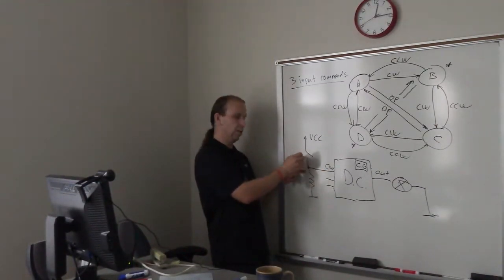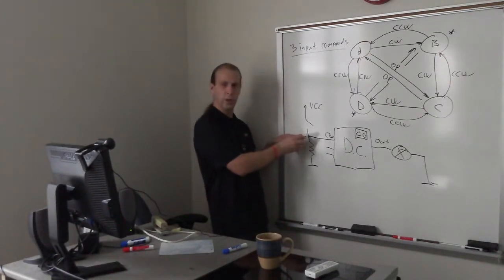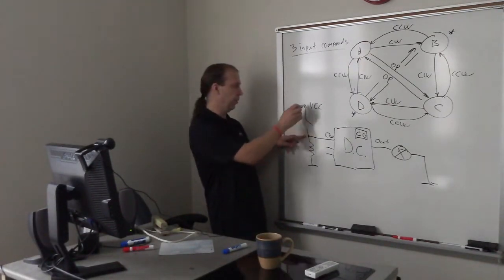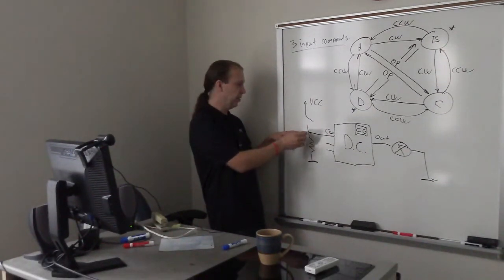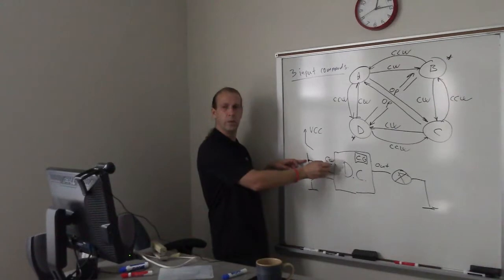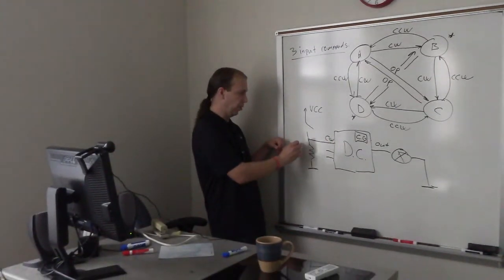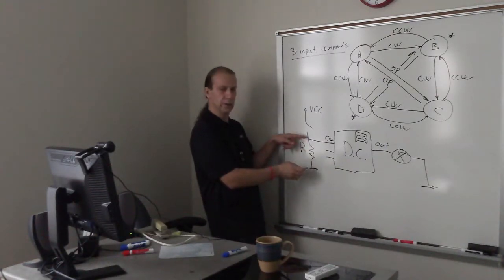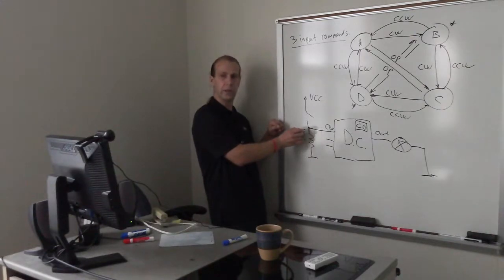When the switch is closed, then we may say that this point is now driven with a voltage. Here we'll have the high level, just because this resistor will drop the voltage. So in other words, if you consider voltages, or potentials, on different sides of the resistor, here it is 0, here is VCC.